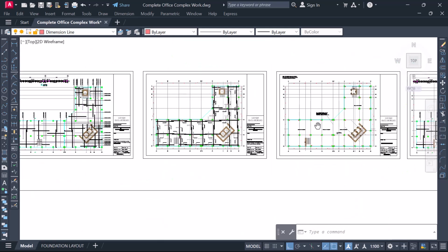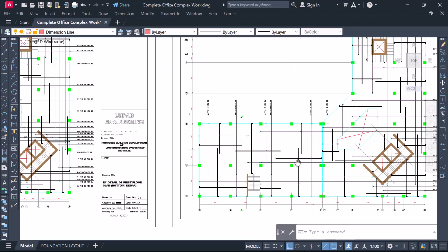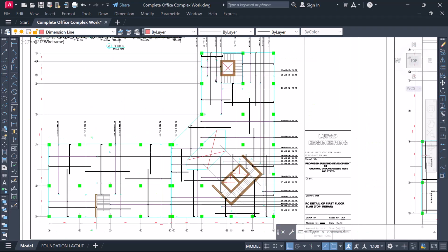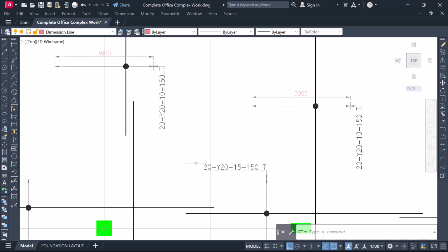For example, you provided punching shear reinforcement during your design, but during the detailing, for the perimeter where you said you want to provide the punching shear reinforcement, the structural detailer didn't provide enough reinforcement or didn't capture the actual region. What happens? It has failed.